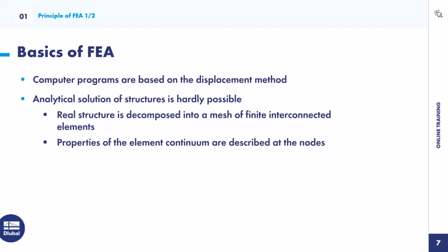And inside the element, we have approximations. There are different approximations and several programs can use different approximations. Also, there's the difference between linear approximations or third order approximations, which would be a more exact calculation, but also result in more demanding computer power.